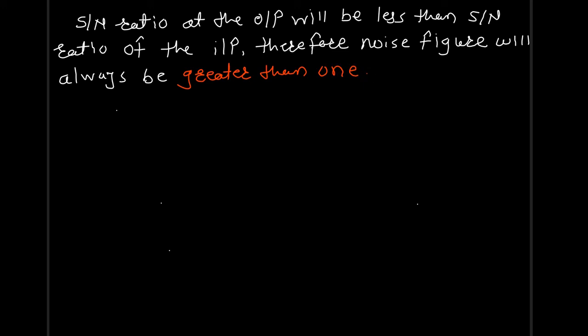An ideal receiver contributes zero noise to the signal, so an ideal receiver has a noise figure of 1 or 0 dB. Such a noise figure cannot be obtained in practice. The lower the noise figure, the better the amplifier or receiver. Transistor amplifiers in communication receivers usually have a noise figure of several decibels.